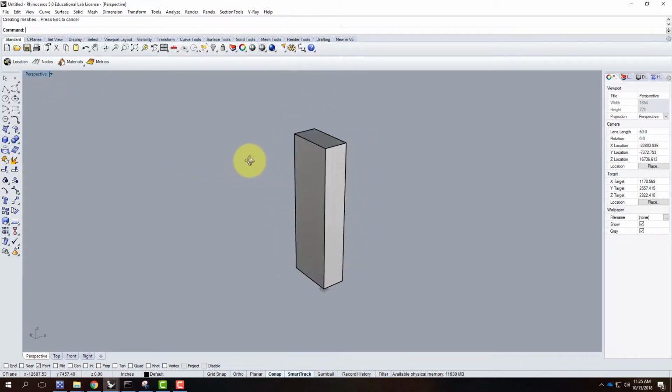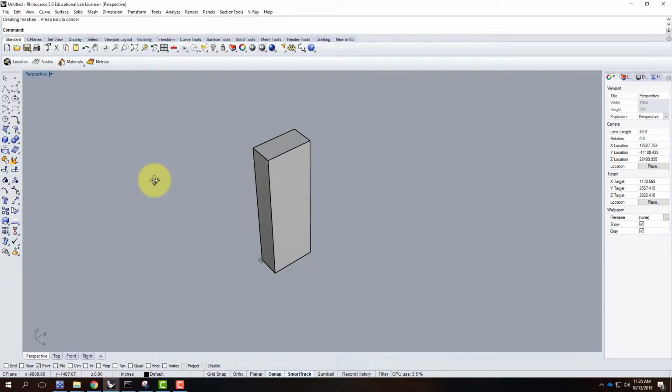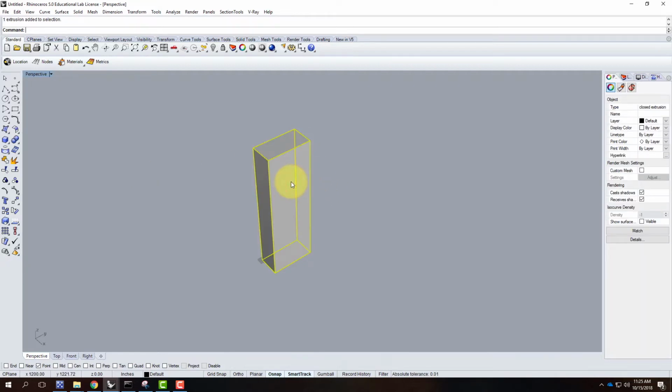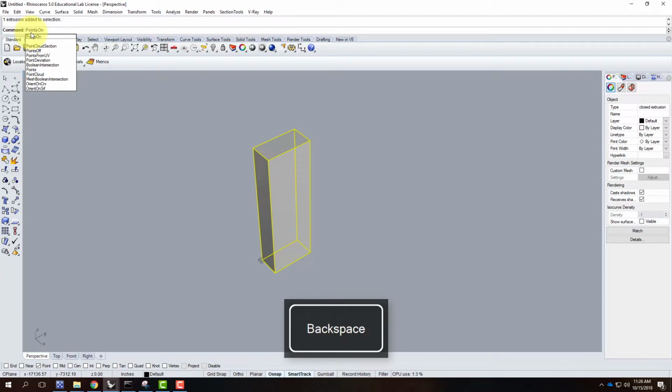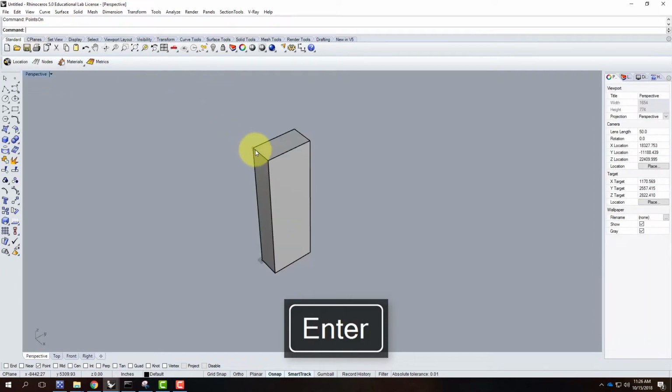At this point, I want to talk to you guys about transformations of shapes. And how do we modify a particular shape and change it into something else. And there are obviously a large variety of different ways that we can do this. But I'm going to kind of show you different pieces of it. So the first option is with any one of these shapes, there are actually control points that define the shape in the first place. So I can come over here and choose to turn my edit points on, or in the command line, I could just type points on, which is written out on your sheet here. And when I do that, I get a few control points.